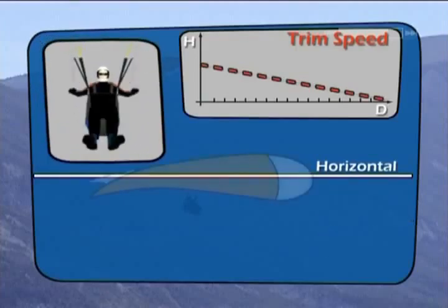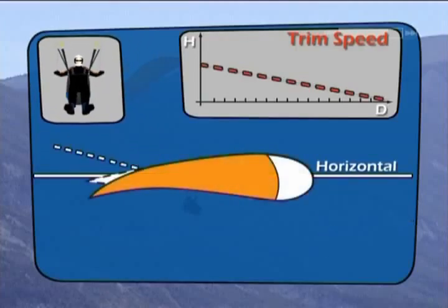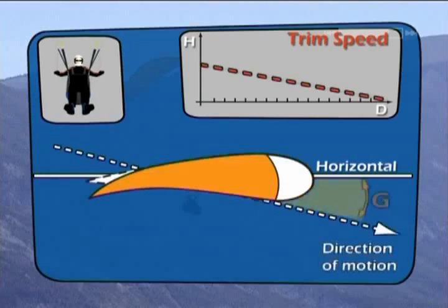Apply the brakes approximately 30 to 40 centimeters to reach the minimum sink rate. The pilot's arms are about level with his shoulders or just below, and there is a positive pressure through the brake handles. Applying pressure to the brake handles will also improve your sensitivity to the wing's movements and increases the internal pressure and angle of attack of the wing, which reduces the likelihood of collapses.